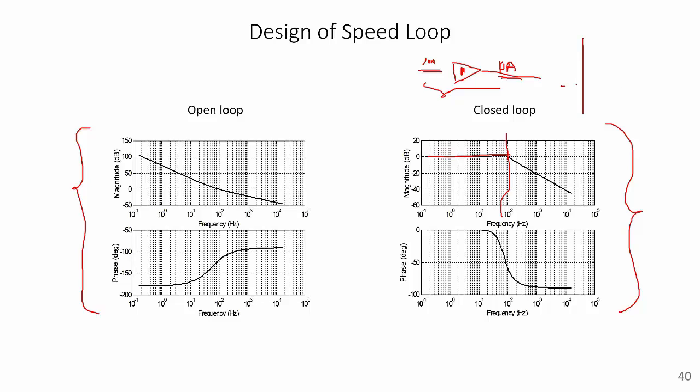So what this basically means is, if you have a step in current from 0 to 10, you want any transient that is caused because of the step to rapidly roll off and settle down. So this is your reference current, and say this is your output current. You want this transient to rapidly settle down to the desired value again, which is 10 ampere. So the rate at which it settles down is going to be controlled by the rate of fall of the Bode magnitude plot.